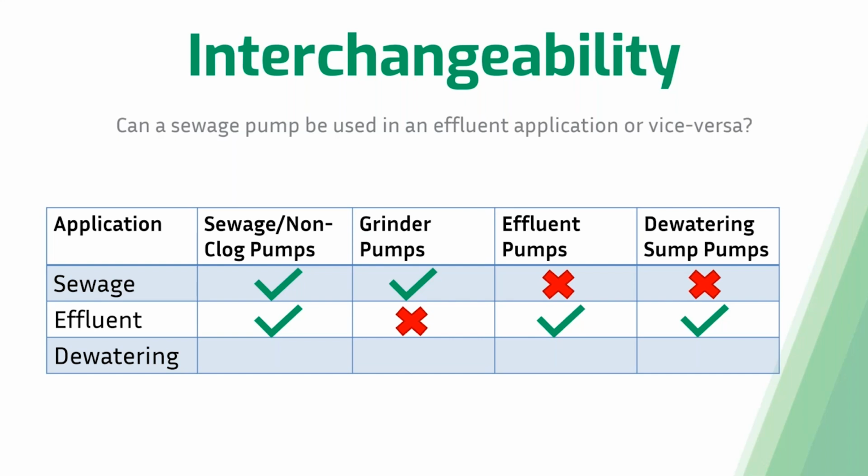All you're doing is pumping water, and there's nothing that you really need to grind up. And typically, you don't want any sort of solids be passed through your system or ground up through your system into the discharge, because that can very quickly clog any sort of drain field that you have in place.